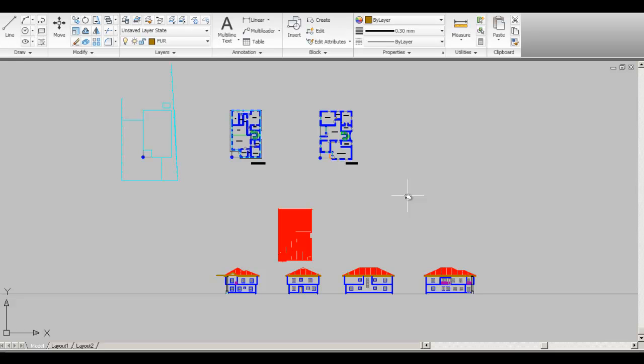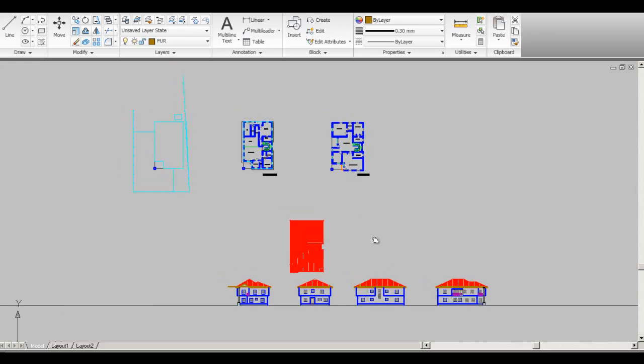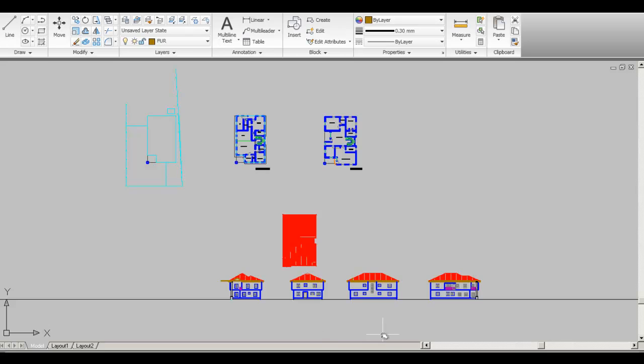Of course, if I have to create my own drawings from scratch, I think I work with Revit, which is a very parametric style of drafting with modeling integrated together. Then you can just draft, and as you draft you have your models out the same way. But from AutoCAD, you'd have to get your drawings out first, then you build your 3D model.